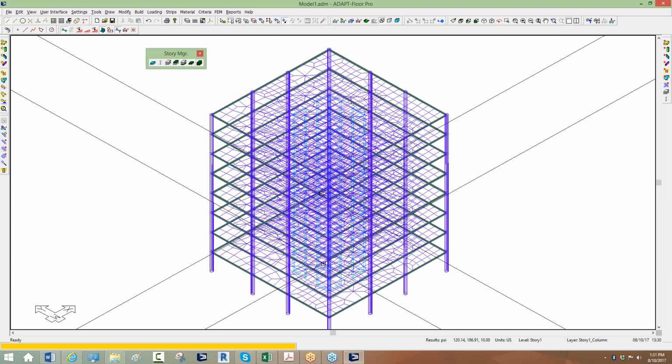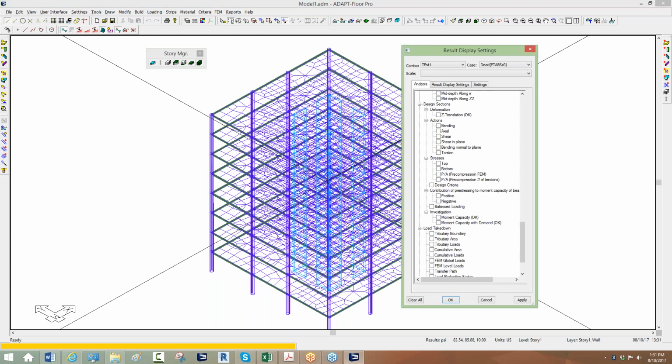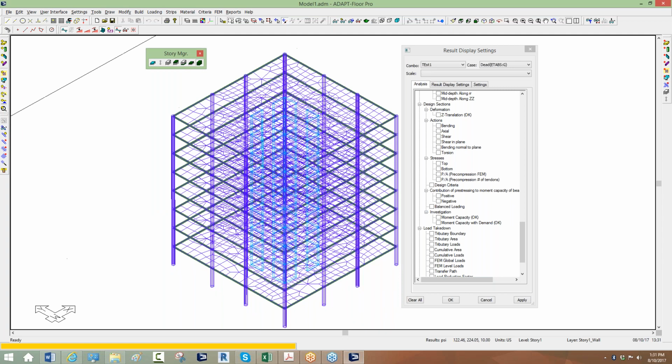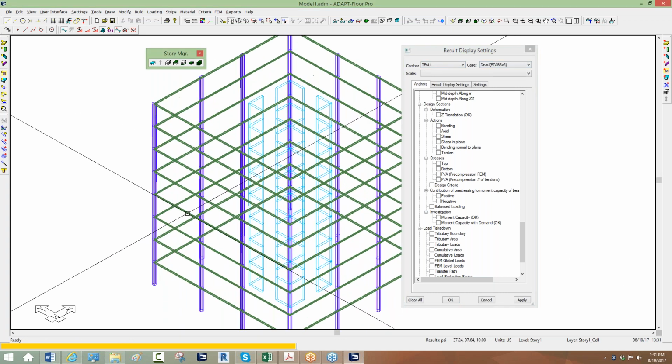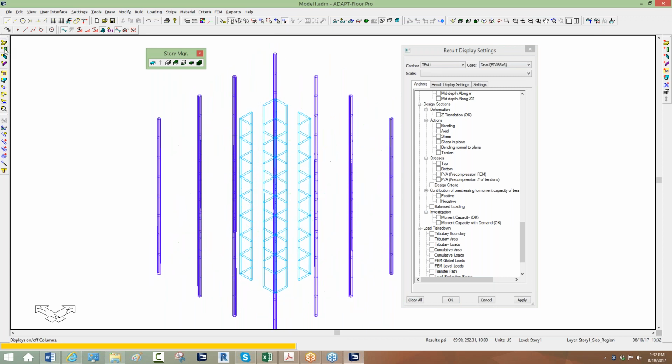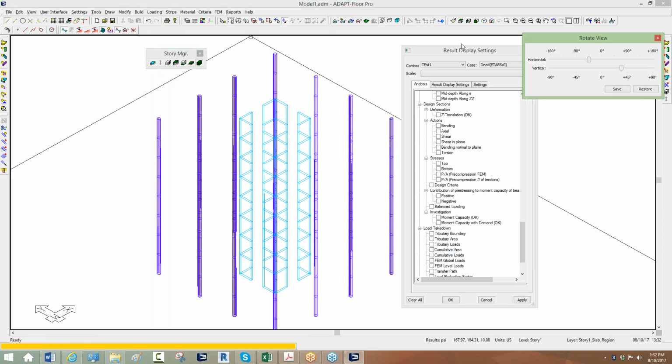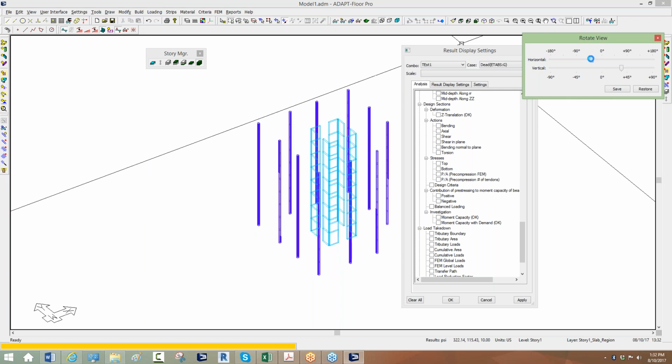And we'll say OK to the solution. Now I have a solution in place for, I think it was, test 1, which was EQX. So we can actually compare results between an Etabs model and a Builder model if you wanted to, assuming that they're apples to apples, the stiffnesses are the same, and there's no modification in one versus the other. The comparison can be done using Builder if needed.